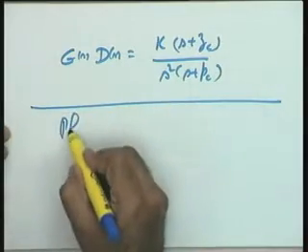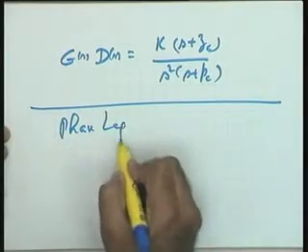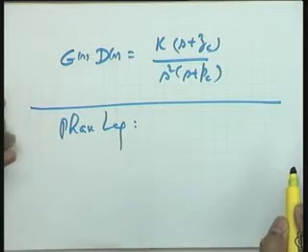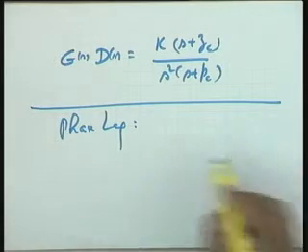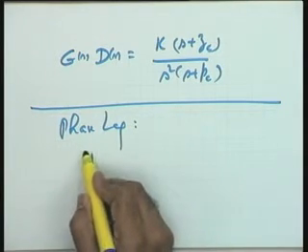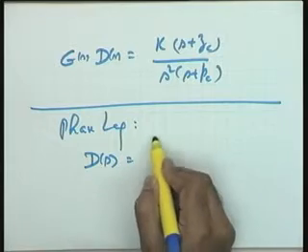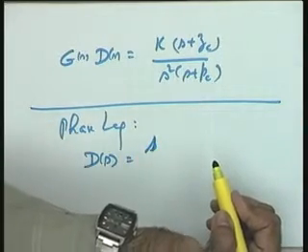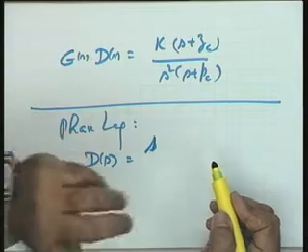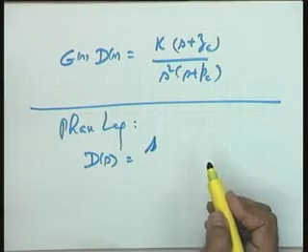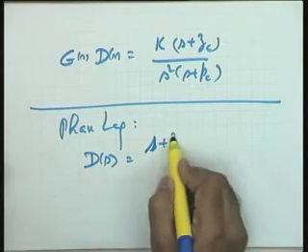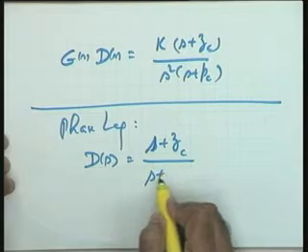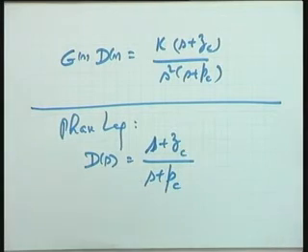Coming to the phase lag network, I have to look at the watch also, and I have to declare it complete today, and therefore I need your attention on the phase lag network now. Gc(s) is equal to K; again if you don't mind, K I can take to the plant, and therefore K into the transfer function becomes the total transfer function of the compensated system. So for the lag network also, the transfer function is of this form, S plus Zc over S plus Pc.